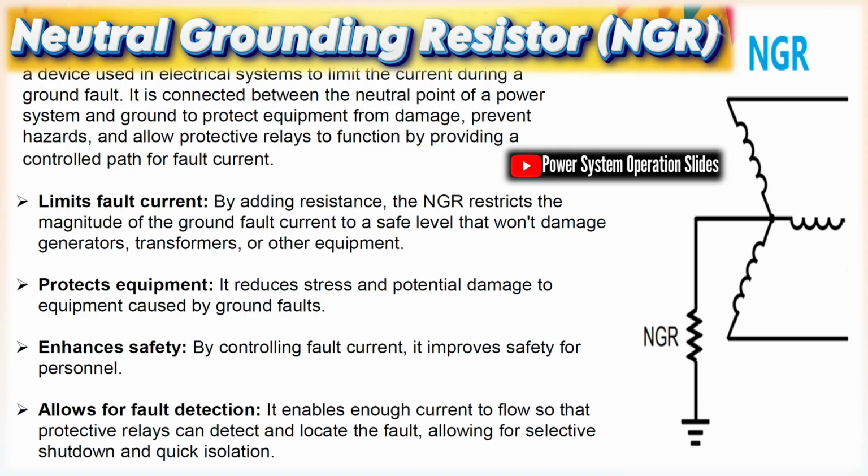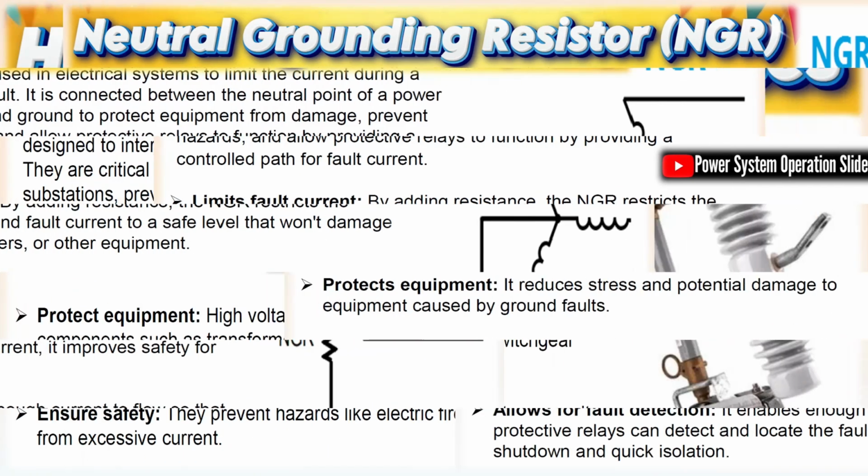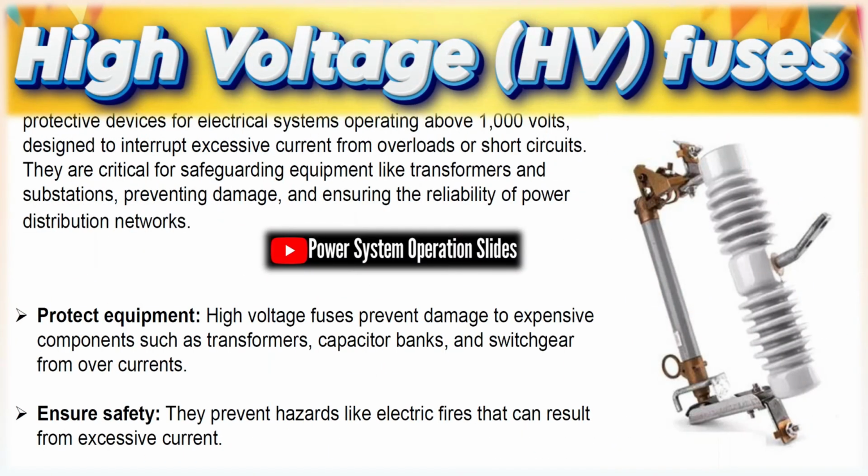Main and transfer bus. Includes a main bus and an auxiliary transfer bus for bypassing breakers during maintenance. Enhances operational flexibility with minimal interruption. Protection remains on the main bus.